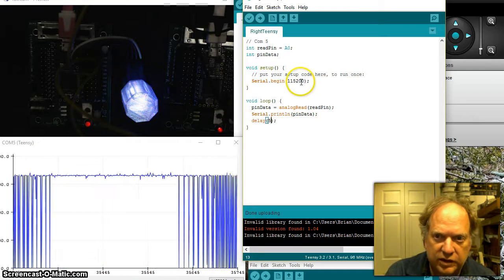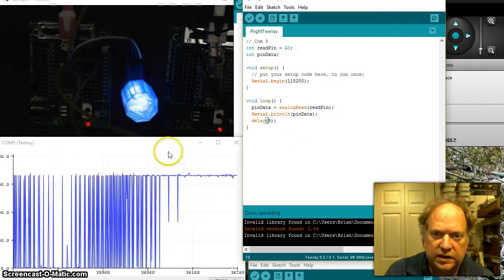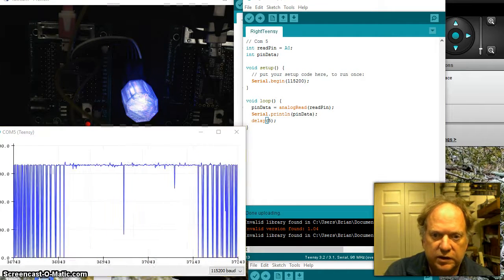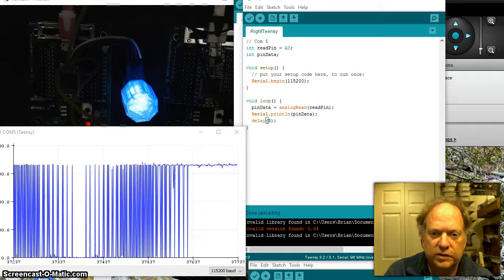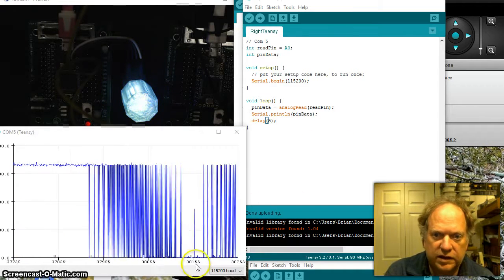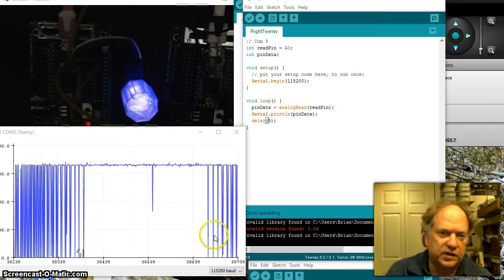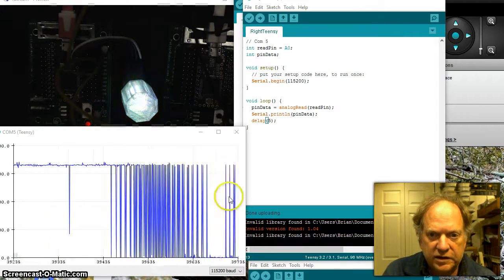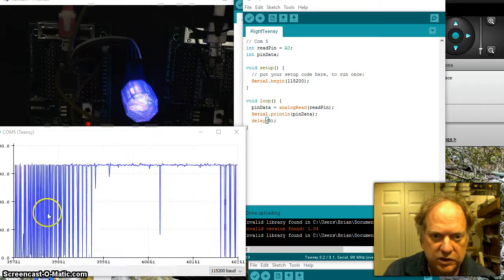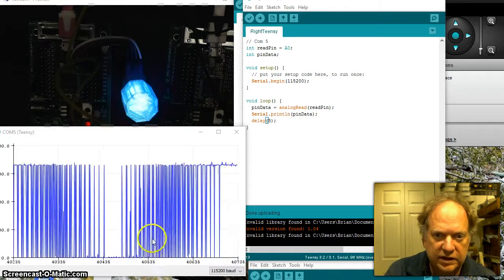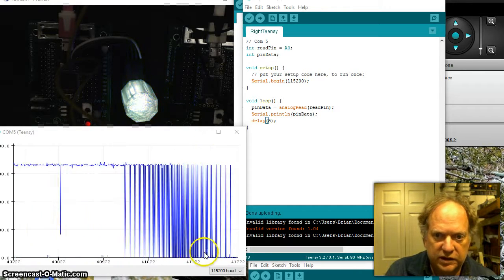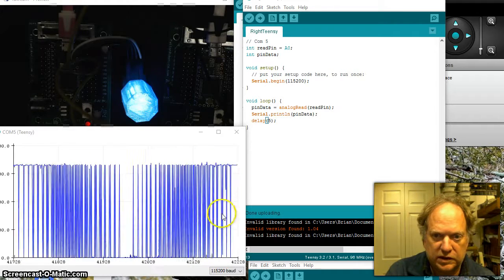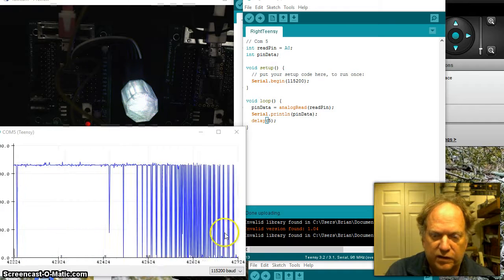I got my baud rate set really pretty high here, 115200. You guys can see in Device Manager off screen here I've set the port to 115200, and of course I have this sketch set at 115200. So everything's set up pretty fast, so baud rate's not an issue. And you can see it's moving across pretty fluidly, a little jerkiness but not bad, and even on this single channel single sample we're seeing the one channel rise, peak, and fall.